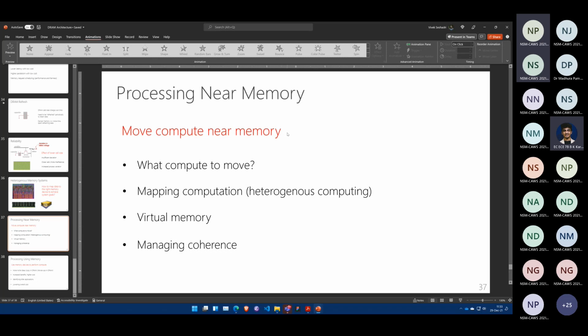It's completely possible to think of whatever processing near memory you're coming up with as a separate accelerator, similar to a GPU, and then these problems won't exist. But if the computation is happening on the same memory modules that your CPU is also accessing, then all these problems crop up. And I don't think there is any clear memory model that has been proposed yet to address these challenges.